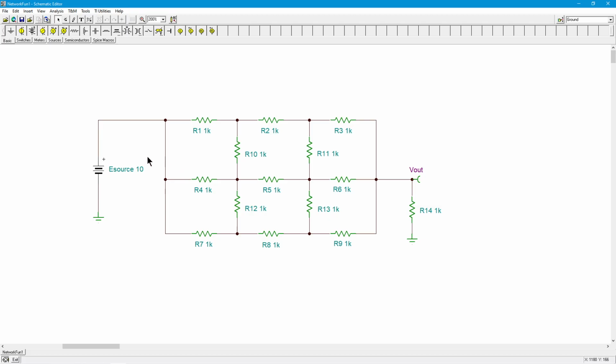So what do you do? Well, you would probably just say, I could do a mesh analysis on here, right? It's kind of big though. If you think about a mesh, you got 1, 2, 3, 4, 5, 6, plus this outer one is 7 loops. If you did a nodal, you've got one node here, and then the 6 in the middle plus the ground, so that's essentially 8 nodes you're going to have to figure out. Now, granted, in both cases, you're going to have a lot of zero terms. So your matrix winds up being kind of sparse, and that simplifies things. It makes the grind through it a little bit easier.